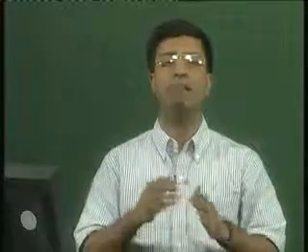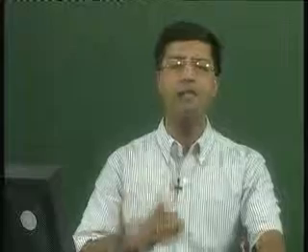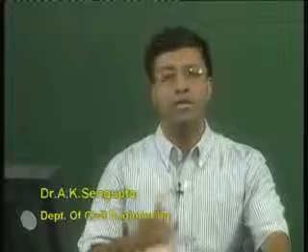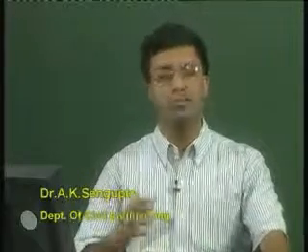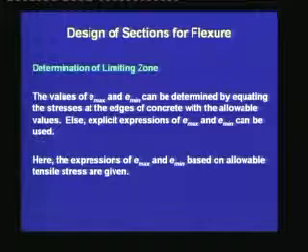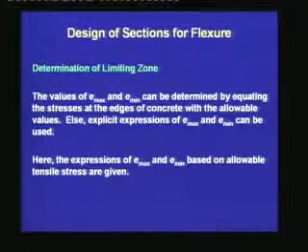One way is to write the expressions of the stresses at the top and the bottom, and equate those stresses to the allowable values. From there, we can find out the E max or E min values. The other approach is to find some explicit expressions of E max and E min so that we can directly calculate those values without calculating the stresses. But both these approaches will give the same result finally. Here, we shall show the values of E max and E min based on the allowable tensile stress.